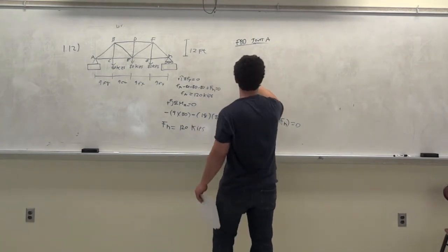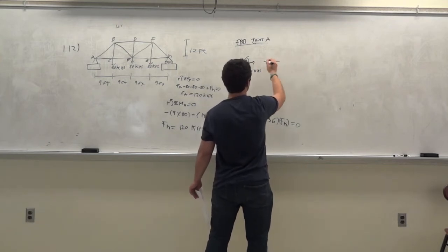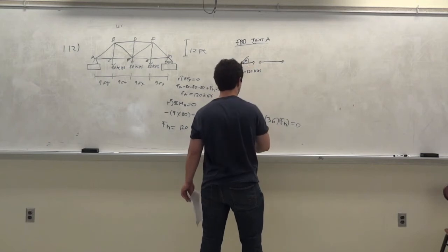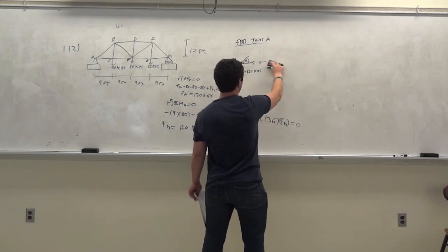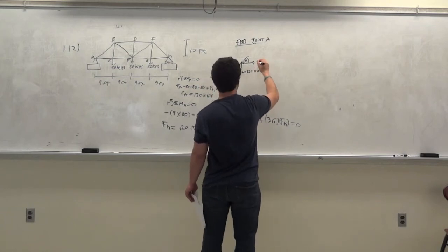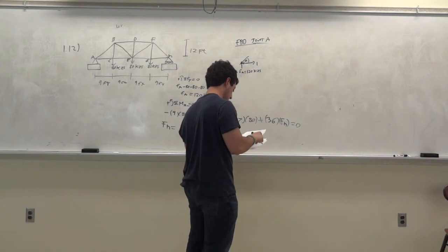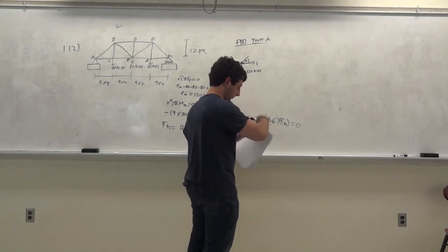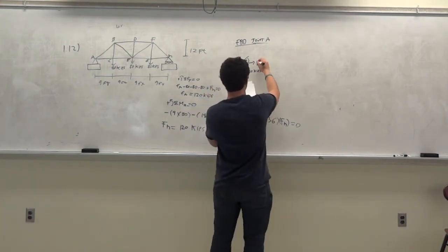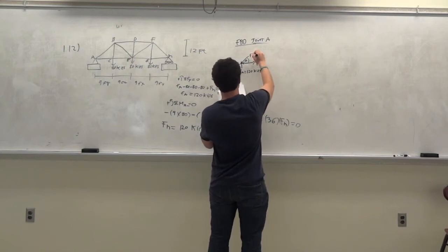The reason why I'm drawing the arrow, this is a joint, right? And the member looks like this. I'll just draw the member really quick. It's in tension, right? So this has to be equal and opposite. That's why I drew it outwards, and inwards for compression. Okay, so this is unknown. We don't know this force. Let me be consecutive with my notes so I don't throw myself off. I called this FAC and this one FAB.